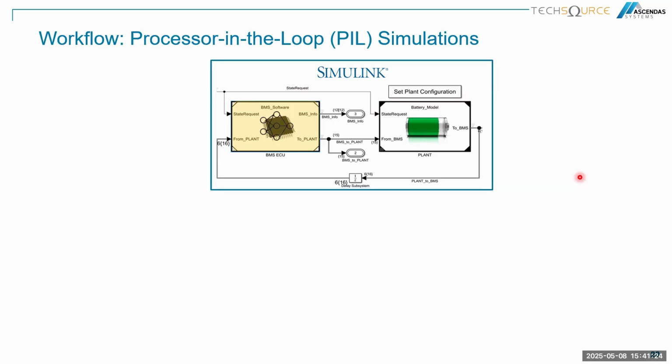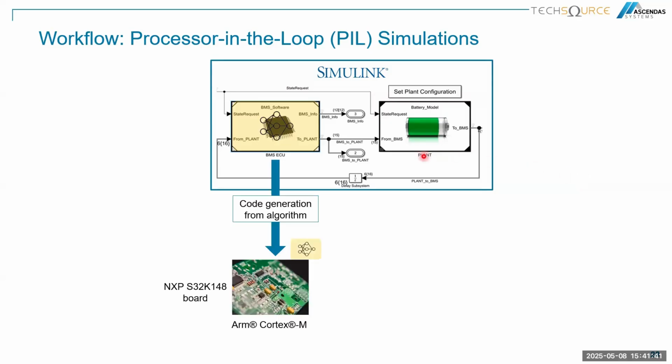We have the Embedded Coder that will deploy your Simulink model to be the optimized C code that fits each brand of embedded board here. So how do we do that? At first we do code generation here to get the optimized C code that matches this ARM Cortex.